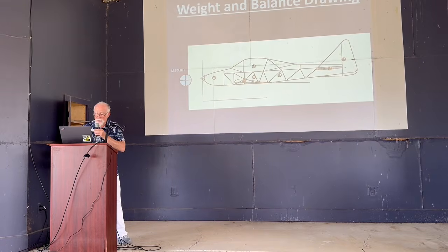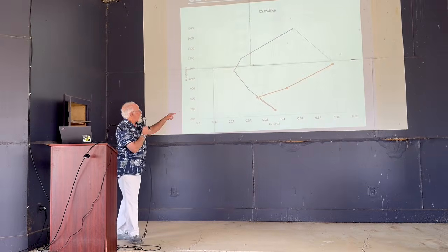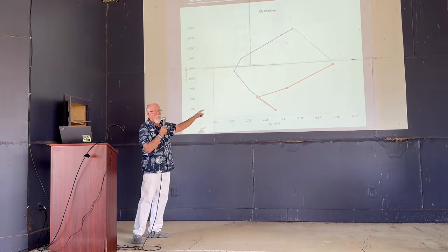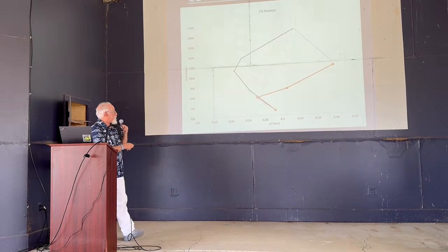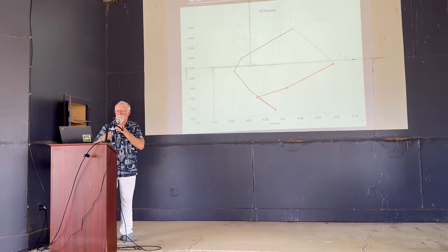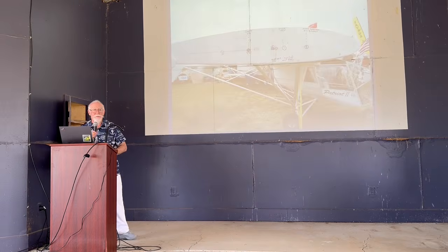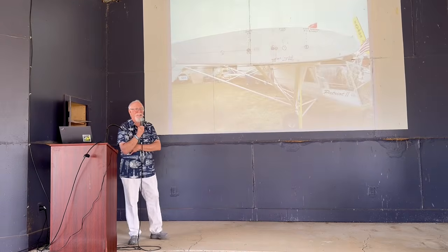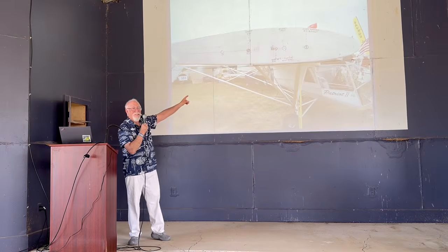And then as you do the calculation, you end up with what we call a potato plot. Each one of those dots represents a different loading on a hypothetical airplane. And the idea is this, the x-axis is mean aerodynamic chord. You want those to fall within the limits. Now, once walking around, I actually found a prototype where they marked it all right on the wingtip. Gotta love that.